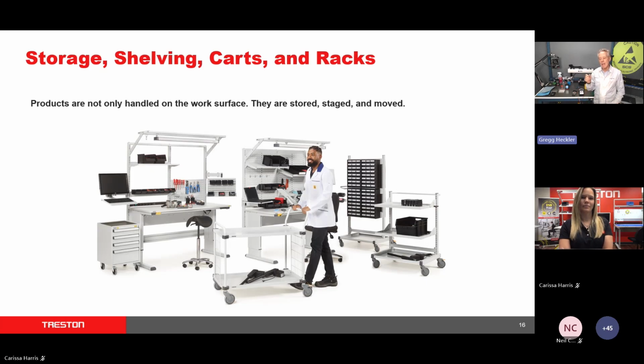So here's what you need to keep in mind, and that is how this thing's getting from point A to point B, and is it unpackaged or is it properly packaged? If it's in static shielding containers, static shielding bags like this, you're familiar with these metallized bags, if it's in a closed static shielding container, then I could carry this across the street if I want to. When it's not, and you're going to take these components on a cart, that cart needs to be grounded as well when it's being transported, and it needs to be transported in static dissipative or conductive packaging materials. And if you ship it, especially, it has to go in a static shielded container. So you got to be thinking at all times, how is it getting from this point to the other point?